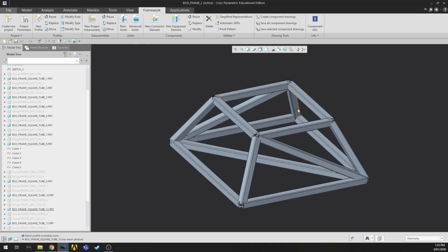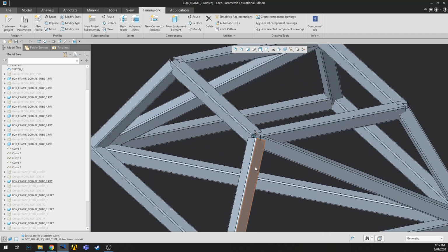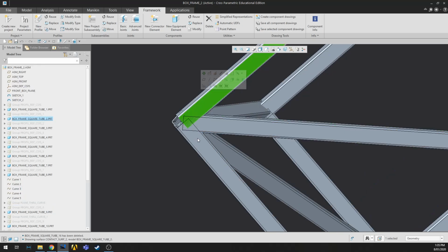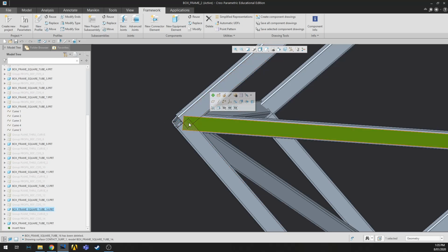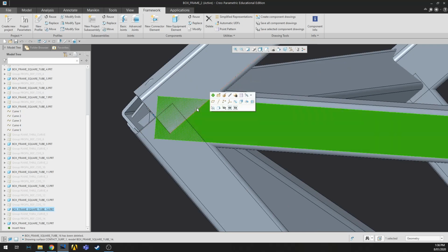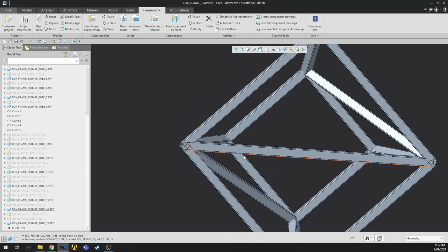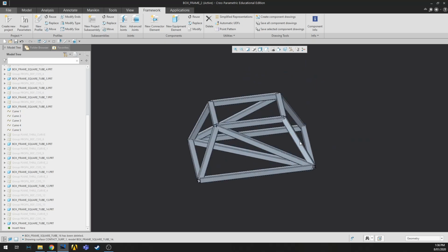So notching is when you take one tube and say this tube down here, we'll look at that surface, it's a good example. Say these two were connected at a miter joint, a 45-degree joint, and then we wanted to bring this tube in here and have it weld in as well. We would notch it, so cut out the material that's overlapping into the joint here, and we would get the sort of inverse of the shape that's left, and then that would let us butt it up nice and neat in there and then weld that up as if it was the one node. So that's notching. And now I'll show you how we do it.